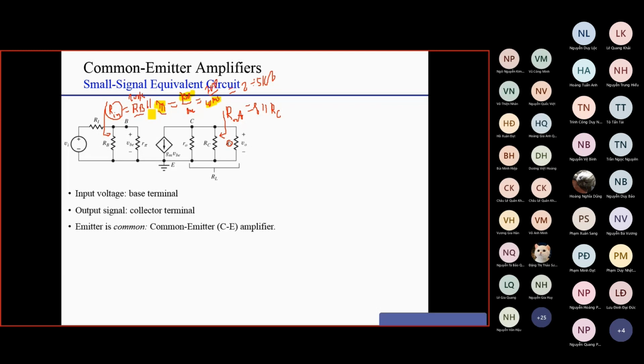Okay, so very interesting. The macroscopic behavior of the amplifier in this case depends on the parameters of the transistor itself. Both the intrinsic parameter of the transistor, that means the DC current gain beta 0, and the external circuit parameter, that means the Q point, the current IC here.